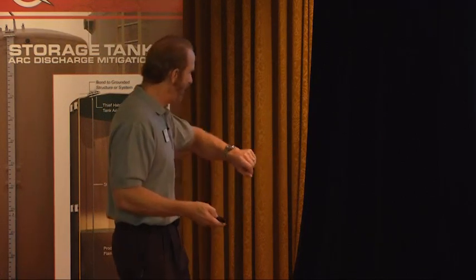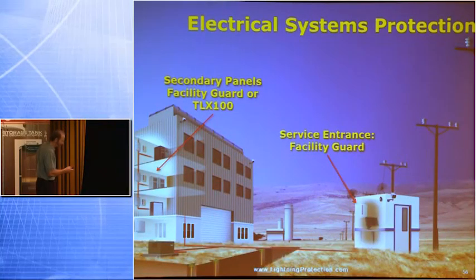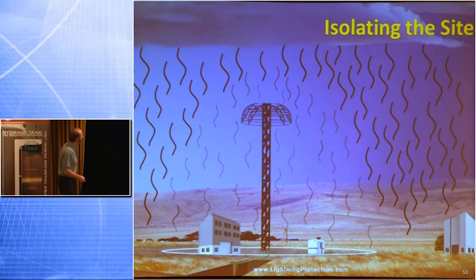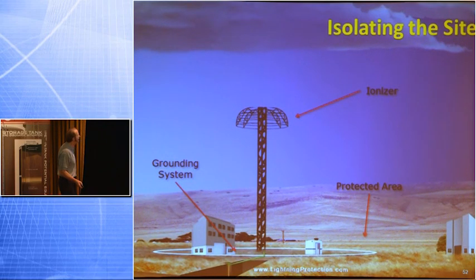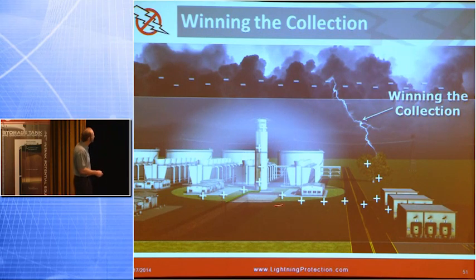Now, I've got just a few minutes left, just a few slides left. When we go back to this slide here, this is our protected zone right here, right? We're not going to have any lightning collection in the zone. But if we had an AC power line coming in from outside into this building, which you always typically do have, that is still a point of vulnerability. We could have a lightning strike off-site to a transformer and come into the power side. So you want to make sure that you also look at all the points of vulnerability to a lightning strike.